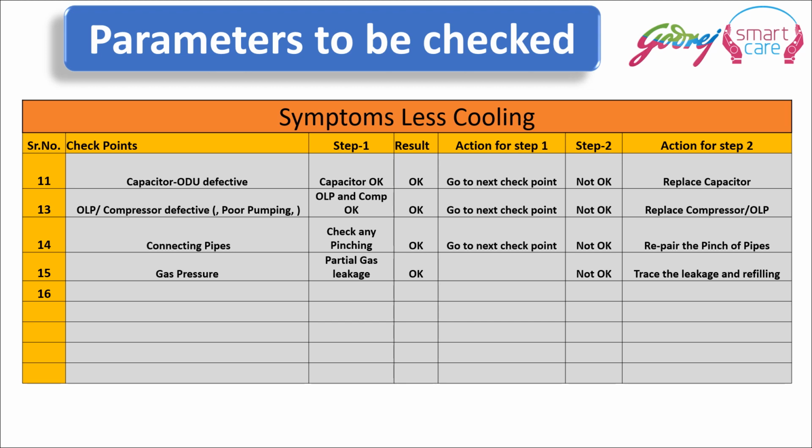Then check the connecting pipe. If there is any pinching, we have to repair or replace the pipe. Then we check the gas pressure. If there is a partial gas leakage, we have to trace the leakage and then refill the refrigerant again.